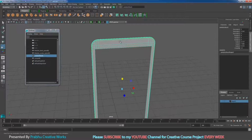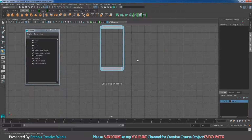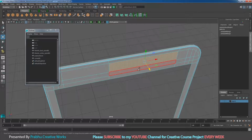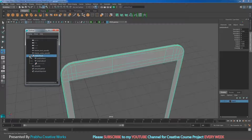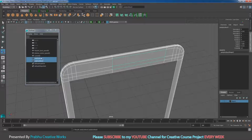For our speaker part and camera part, shift right click and choose insert edge loop, go to front view. You want to insert an edge loop a little bit over here and then here, like this. Now go to object mode, go to perspective, right click and choose face, select this face, shift select this face. Now go to edit mesh and choose extract. That means it will be extracted into 2 parts. Extend this group, select both objects using control, shift P to unparent that group. When both objects are selected, go to edit, delete by type and choose history. So all our history will be gone.